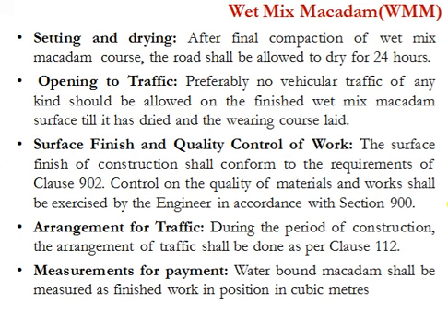Then, opening to traffic. Preferably, no vehicular traffic of any kind should be allowed on the finished wet mix macadam surface till it has dried and the wearing course is laid.